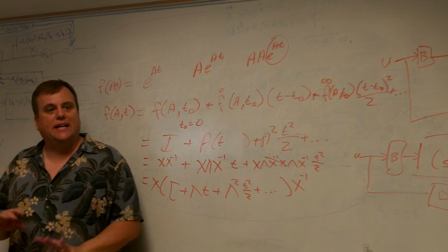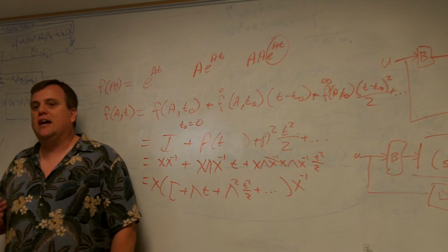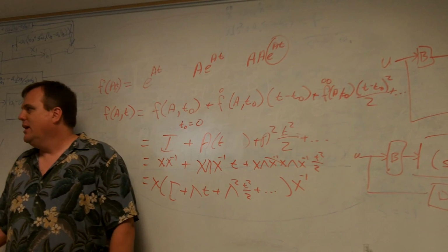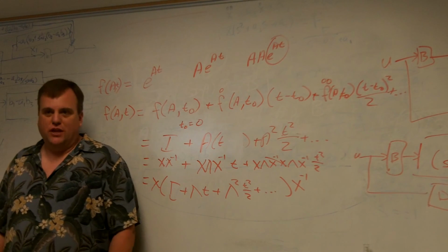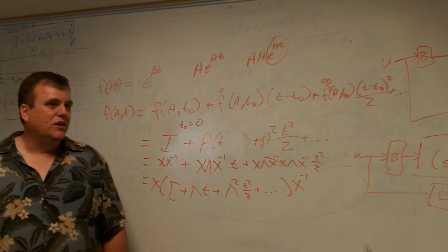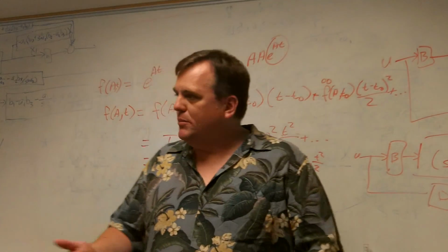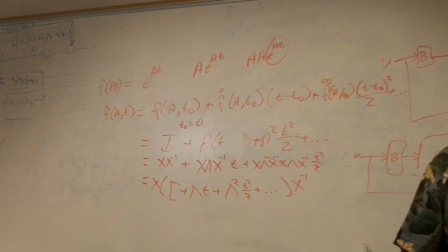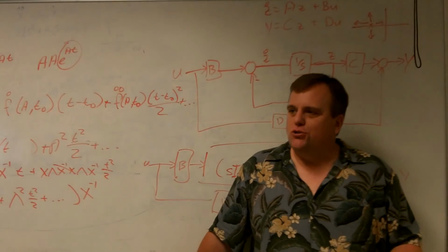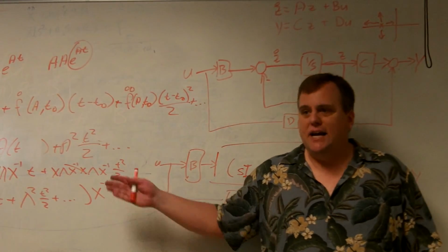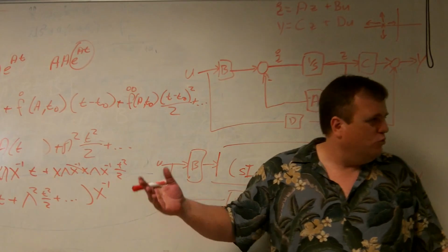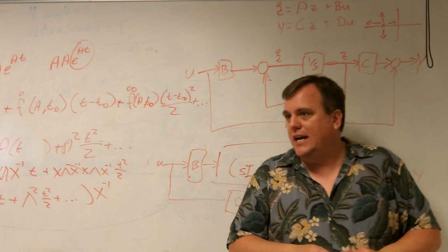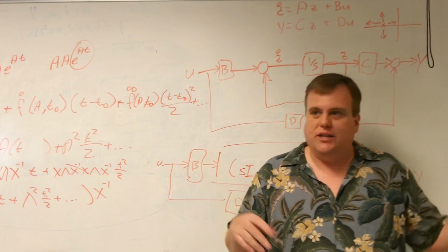So the whole game now, for any control you do, is to check to see, does the net result after your control has been applied, do the eigenvalues of that system end up having negative real parts? If they do, it's stable, you're done. Okay? And now you can pick any control you want. You're not limited to just the ones that they want to give you according to a form. You can pick anything. So this is actually even more general. So it's slightly easier to develop. It is easier to manipulate. It naturally shows you how you program it in some reasonable fashion if you think about it, right? And it also gives you the added bonus of, on top of simplicity and everything else, it's elegant to write.